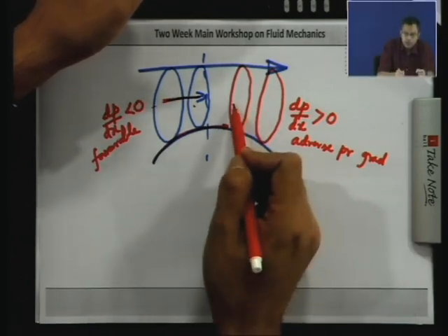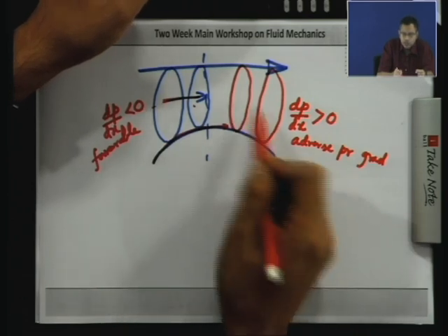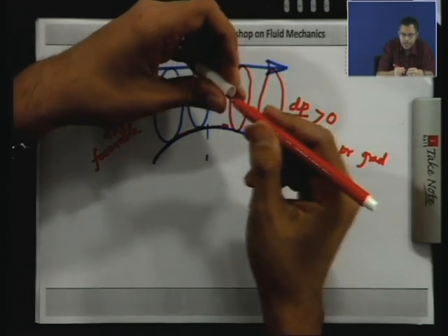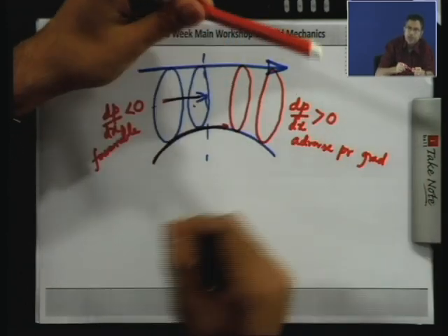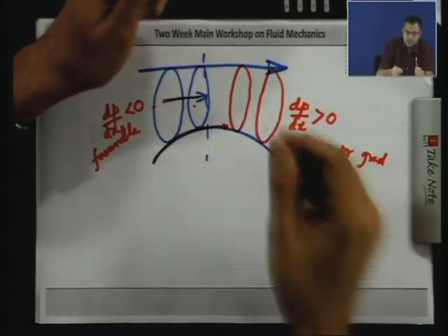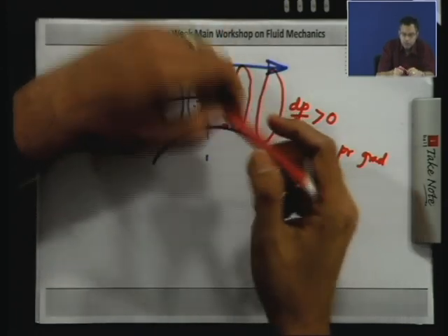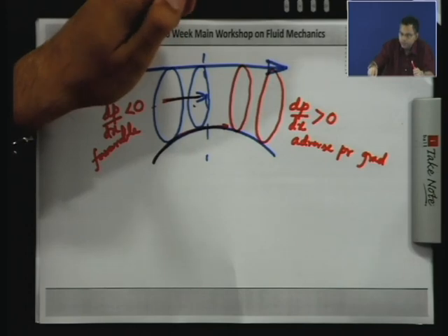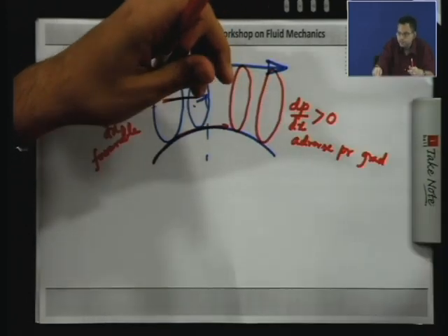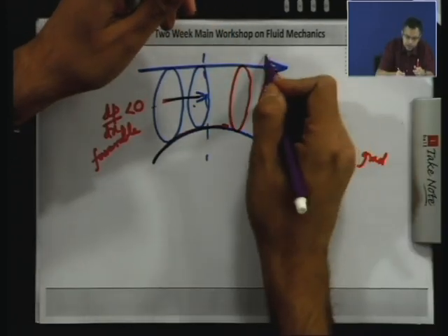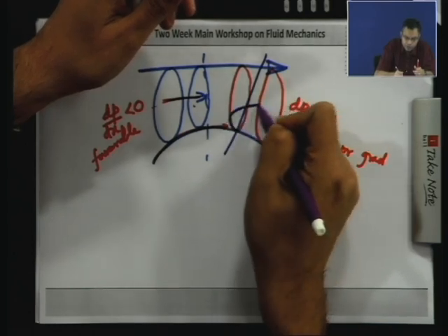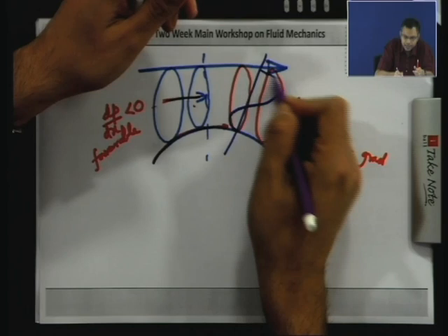So instead of the fluid flowing in the forward direction close to the wall, the fluid can start moving back. The boundary layer is defined based on a monotonic increase in the velocity, so let us say that there is a back flow. Let me try to draw a schematic of the velocity profile. If there is a back flow, the velocity profile may be something like this.